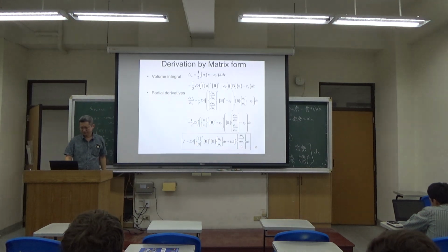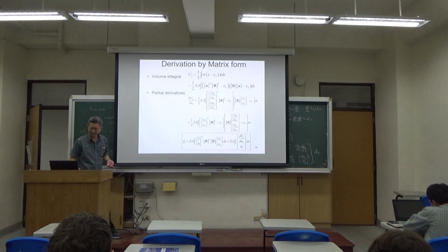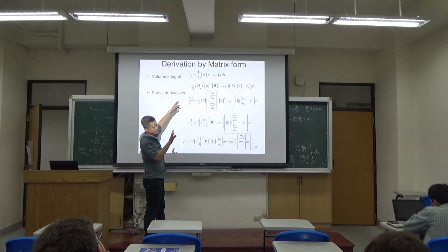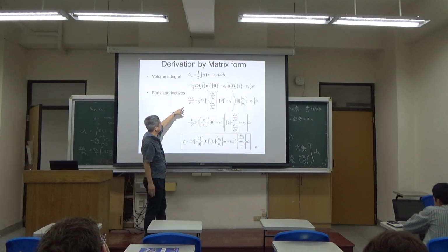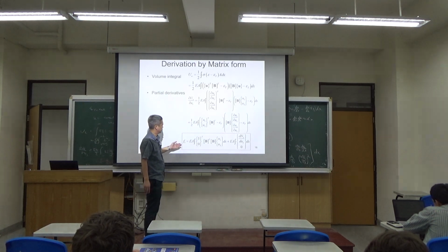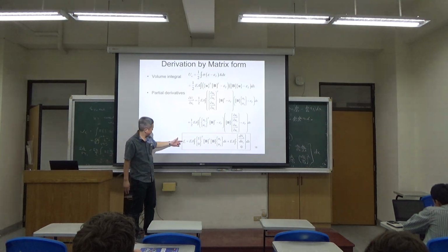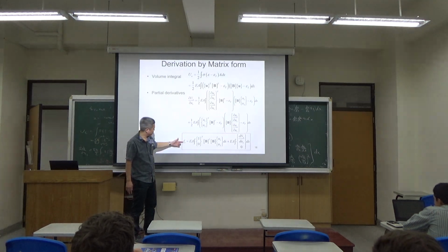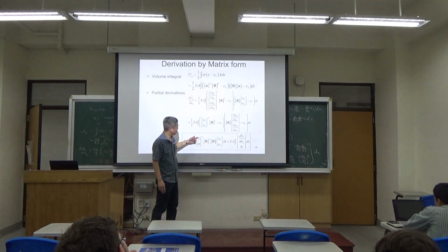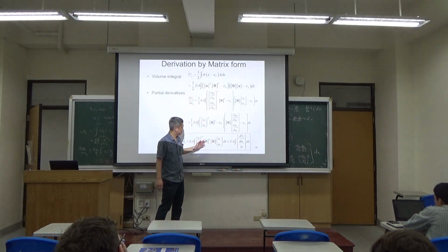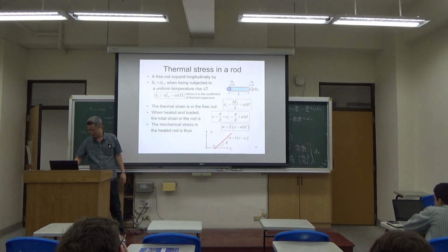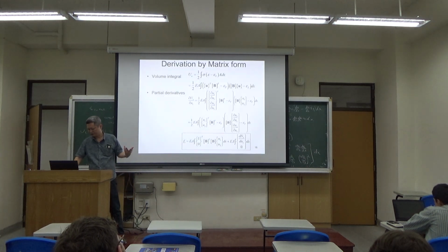Okay? So our operation beforehand now can be done in the matrix form. But it's just kind of a re-expression only. So you can do this operation by matrix. Okay? The first derivative with respect to displacement U1 will give you the first row being non-zero. And then the rest is the B matrix multiplication with the rest. And if you do the same, then you will eventually find F2.